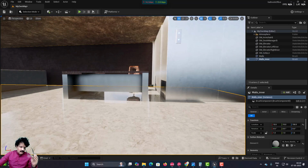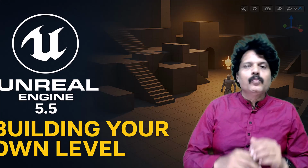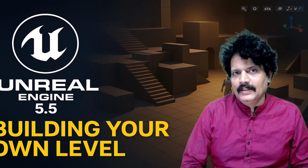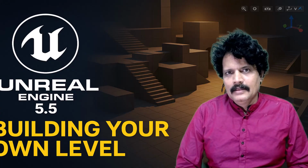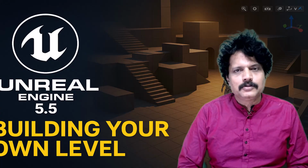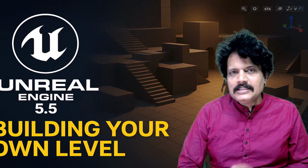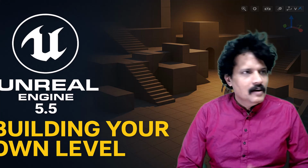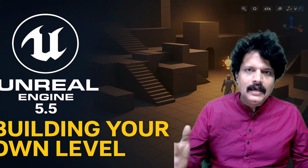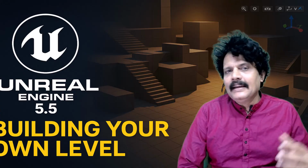Okay. So, in this session, on day 1 of our virtual filmmaking process, we have just explored, as the tip of the iceberg, the basics of Unreal Engine. In this session we created a level, we added atmosphere, we added a room, we built a room using geometry brush, and then we added the components.